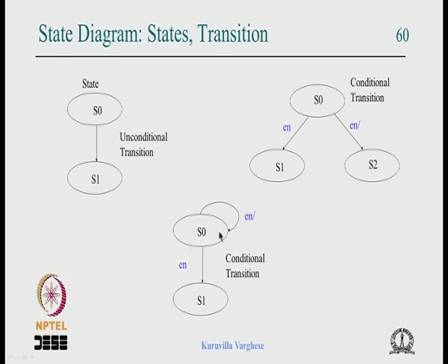Like you can imagine that the controller initializes something and you are waiting for some signal from the circuit, or there is a data path which is doing some computation, you enable that, you started that computation, and the state machine is waiting for it to get over. When it gets over, it continues and does something. So it is a very useful thing, it waits for something to happen and remains in that state.